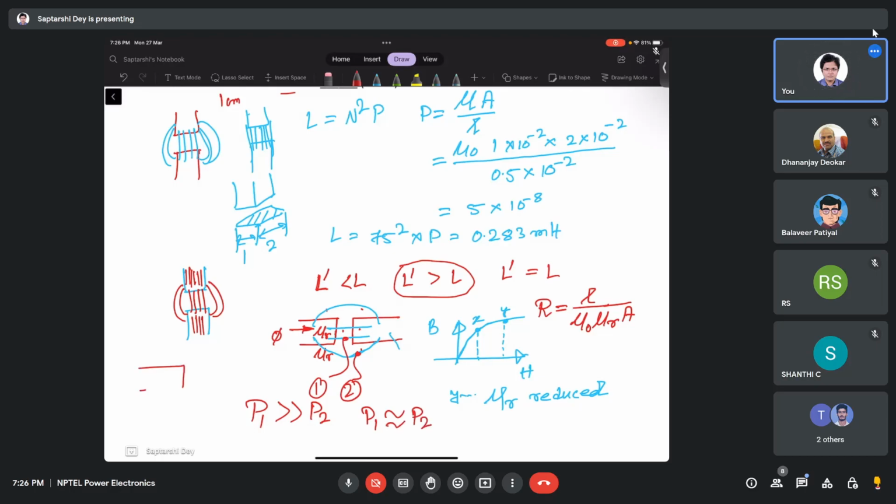So the flux will now see, throughout this area, a medium whose permeance is more or less the same, so it will more and more take these paths, because to the flux it doesn't matter where it is flowing, it only understands mu r. More and more it will flow like this, or in other words, the closer to or beyond saturation you work, the more fringing we will get to see. This is an interesting point to note.